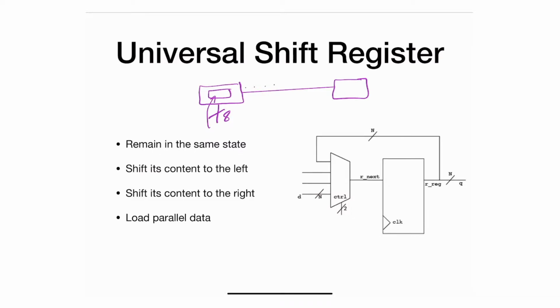And the other one here, which is also a universal shift register, is actually shifting. For example, if this is shifting to the right, this is also shifting to the right. You're loading them 1 bit at a time, and after 8 you can read out the 8 bits that you inputted. So one use of universal shift registers is if you have a couple of them: you do a parallel to series in here to send the data, and then a series to parallel to receive it. So you transfer the data from one point in the system to the other using only one wire, because for some reason you can't have more than one wire.